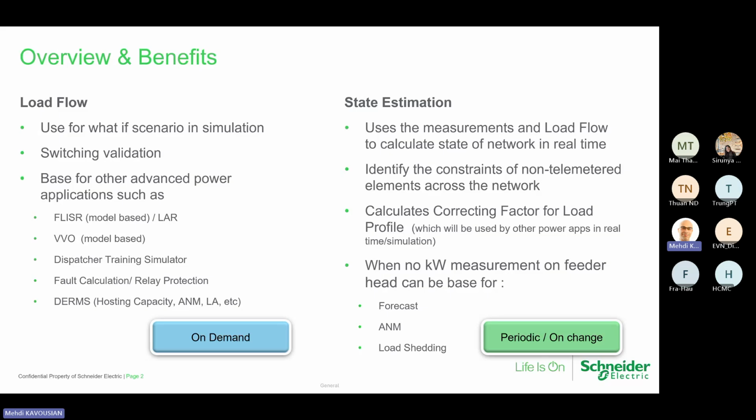They could use load flow when they are model based. What is the state estimation? State estimation, from some point of view, uses the load flow input data, so static data like impedance or switch status, or everything that load flow could use, but also utilizes the measurements.